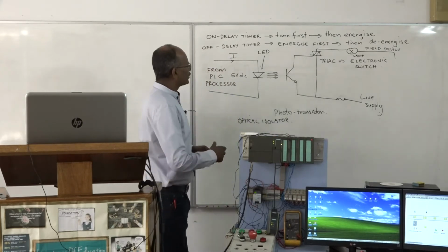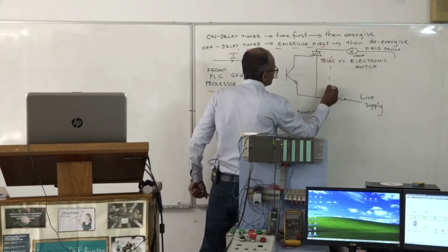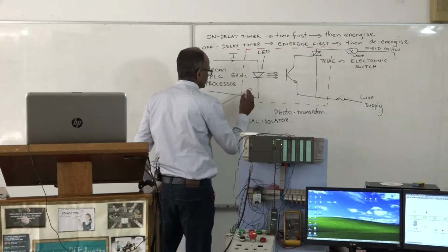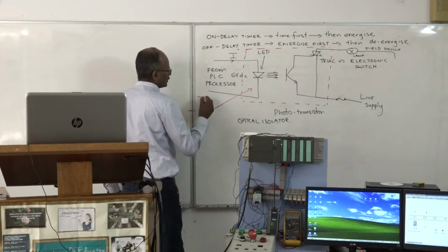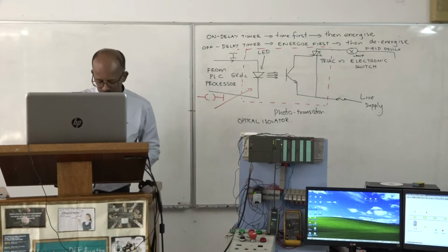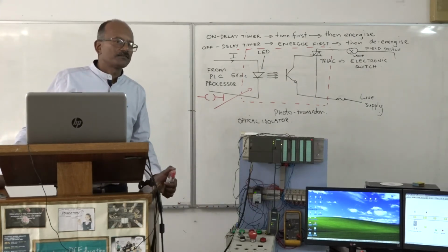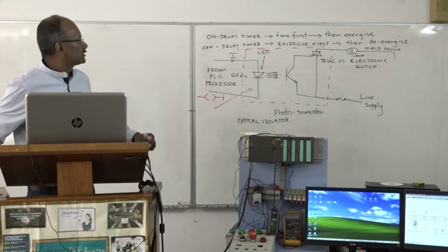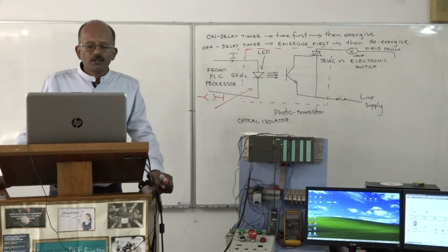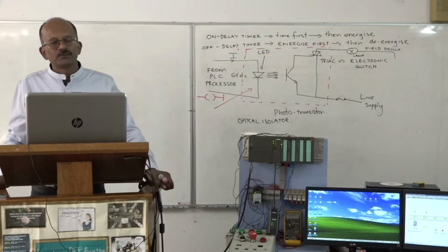So this whole circuit here, all right, represents now what we call my output contactor or my output coil. Remember, it is not a physical contactor, it is not a physical coil. Attached to that output, you could have as many normally open or normally closed switches that you want that are built into the PLC.